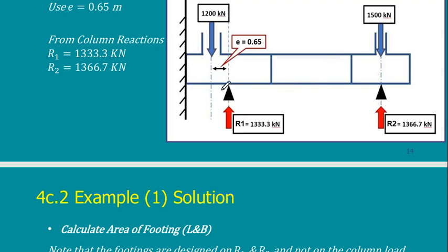And here, I shifted it. How much did I shift it? I don't know. This is the target of my design. I need to know the exact location where I can put this red arrow so that these two are exactly having the same effects as these two blue arrows. How to do this? Take the moment at this point.